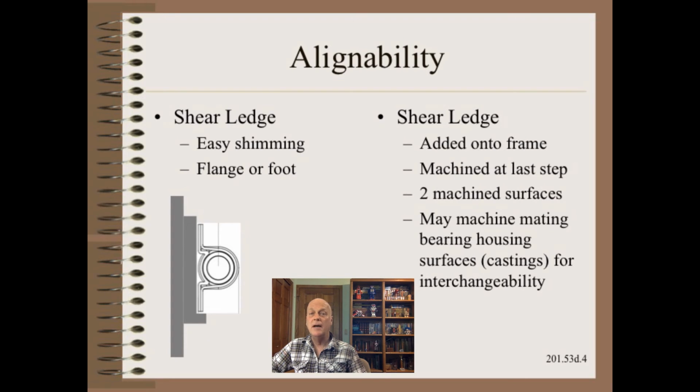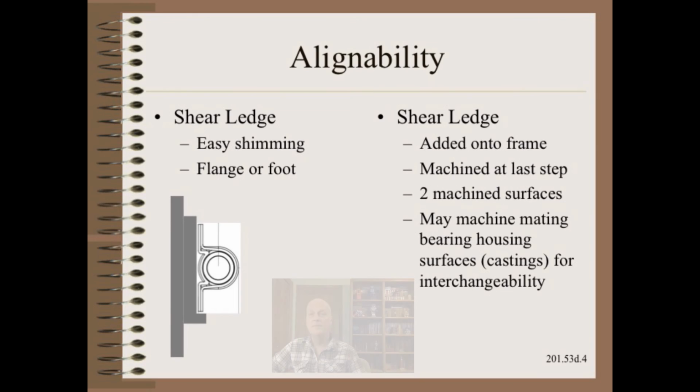If you do dowel, however, there is no doubt on the procedure. You will drill, then ream, then drive the tapered dowel pins just after alignment, but prior to starting the machine. One or two realignments can take place by re-reaming the holes to the next bigger taper pin size. After that, you need to make new holes.